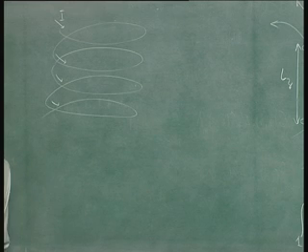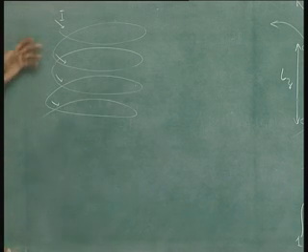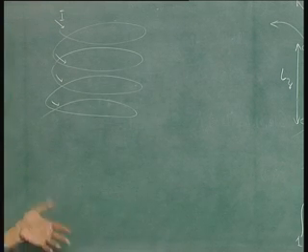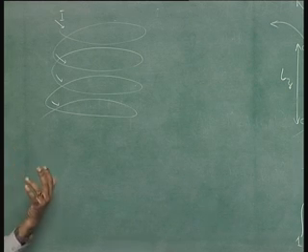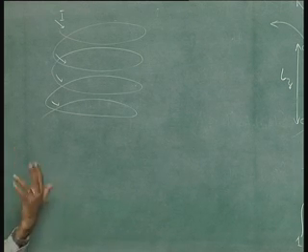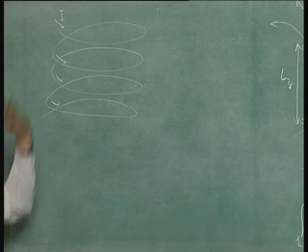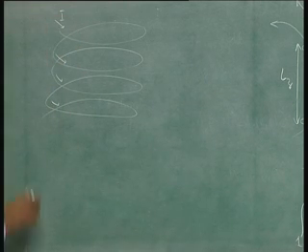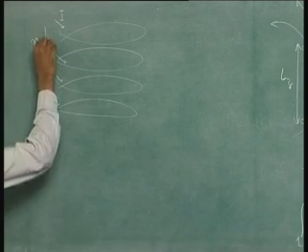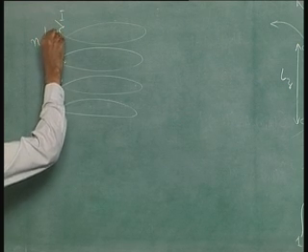In the concept of inductance, we have built into it the number of turns per meter. We could actually have defined inductance per turn and then generalized for an n turn system, but it is so common to have multi-turn coils that we just built the number of turns per meter into the definition of inductance. So, let us say we have n turns per meter.